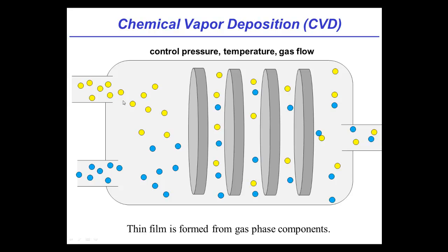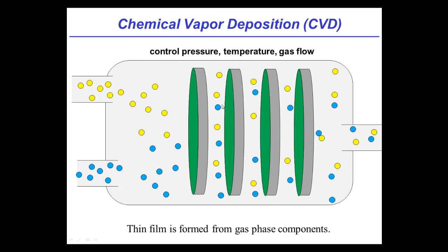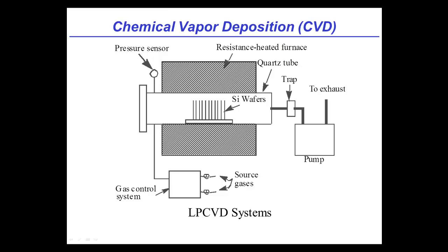Okay, so having talked about this, let's look at a slightly more realistic reactor. What we're going to do is, as you see, we grow this layer. Let's look at that in a real reactor. Michelle, maybe you can walk through a so-called LPCVD system. Sure. This is almost identical to what we showed you in the slide before. We just thought we'd show you the different components and emphasize the LP part of this. So here you have a tube. This is very similar to the enclosure we showed you before. And in this tube will be something called a boat. And you will load your wafers standing up and down on this boat, as Vivek said.